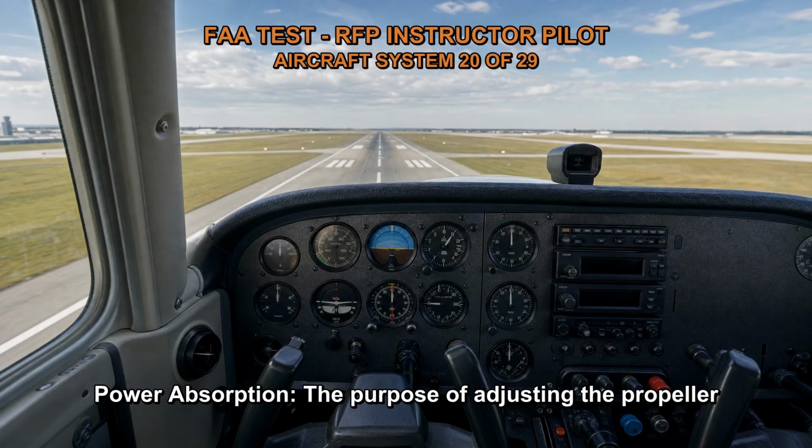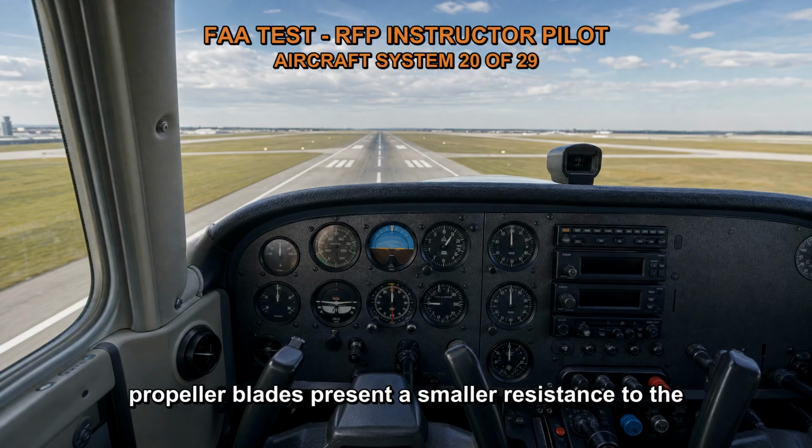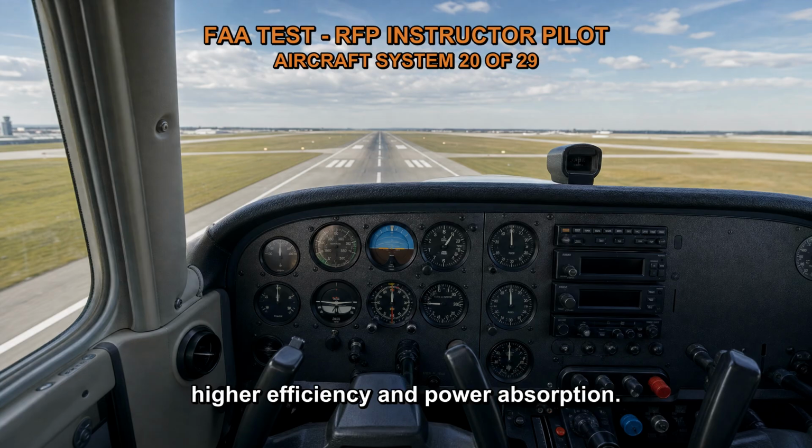Power absorption. The purpose of adjusting the propeller blade angle is to allow it to absorb the maximum amount of engine power. By setting a small angle of attack, the propeller blades present a smaller resistance to the airflow. This reduces drag and allows the engine to transfer more power to the propeller, resulting in higher efficiency and power absorption.